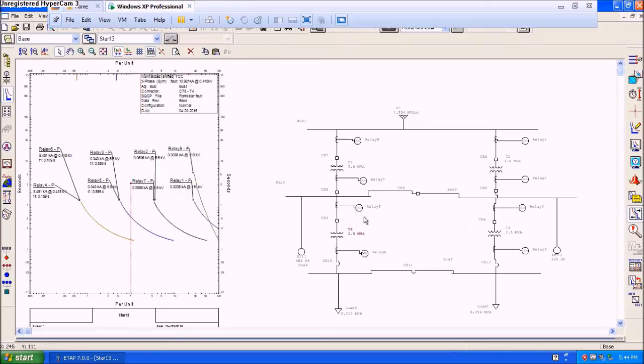As you can see in the graph here, relay 4 and 6 are the first to cross this line. This is the tripping line. These two are crossing the tripping line. That's the reason they are tripping first, and it is tripping at the second. So you can clearly see from the graph, this is the curve for relay 4 and 6. They are tripping in less time, so only a very small portion is cutting this line, while for relay 3 and 5 above, you can see a large section cutting the tripping line, because their time setting is greater than that of relays 6 and 4.